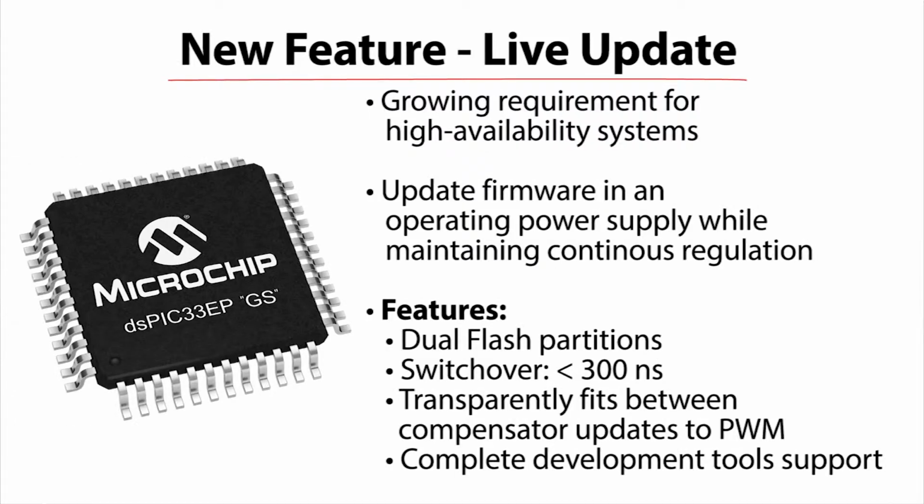Well, I could imagine, because you have to understand the system perfectly, understand the timing. Your timing's got to be spot on. And then, of course, your code segments have to be short enough to fit into those gaps. You're switching over all of the code, so you've got a whole new version in the new code drop that has been loaded by your bootloader into the system. And then when you switch over, we switch from the one flash panel to the other flash panel and immediately start executing the new code. The first thing that new code does is maybe reinitialize some variables, but then it gets right back to its business of regulating that control loop.